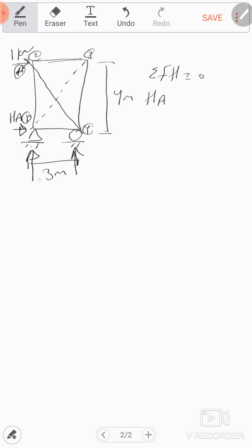And this is VA and VB, the vertical forces for node B. Plus 1 equals 0, because I don't have any other horizontal forces or reactions. So HA equals minus 1.